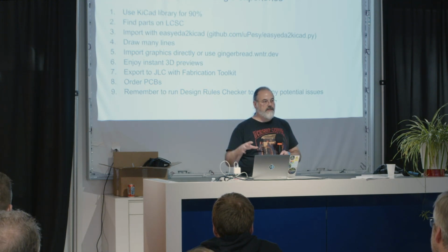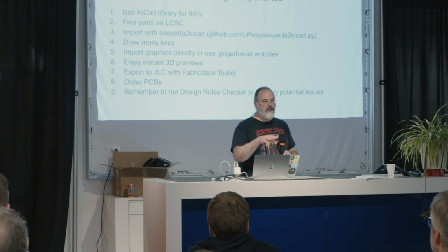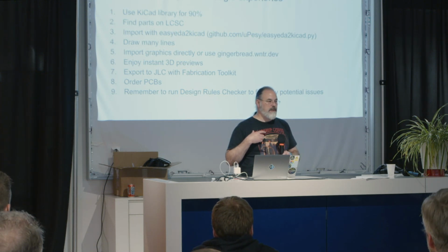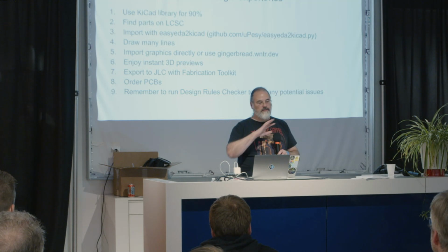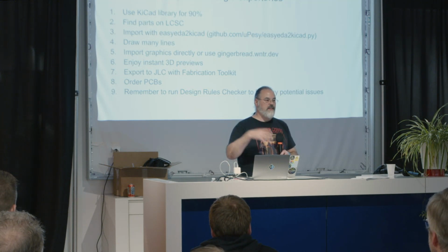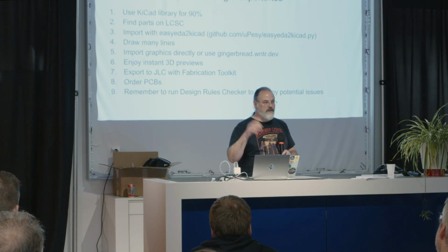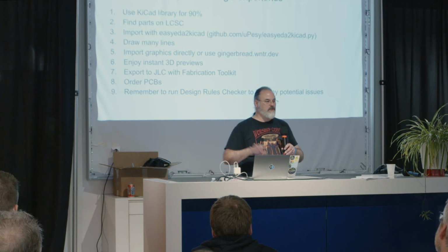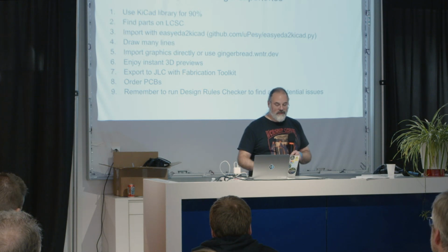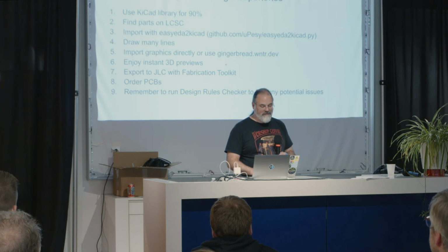It goes through and it does a process where it'll kind of downsample some of those things. And so some of you all have this art pen that I made, and it just has tons of graphics that I had traced in Inkscape, and there's just bazillions of little corners and curves and stuff like that. First I pulled that in, and it was just sort of bogging down, especially the copper, because it's doing all kinds of DRC checks and stuff. Used this, and it was super snappy. The tool is amazing. Hopefully I have enough time to show you all later.